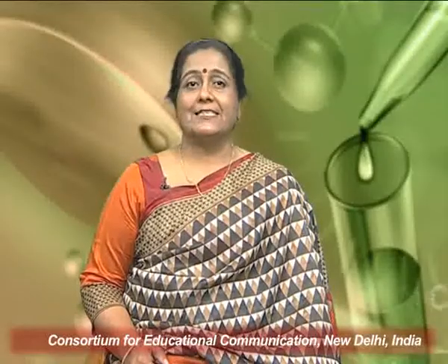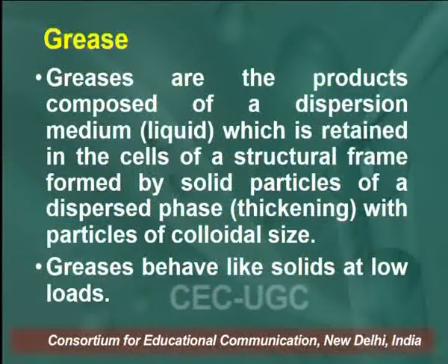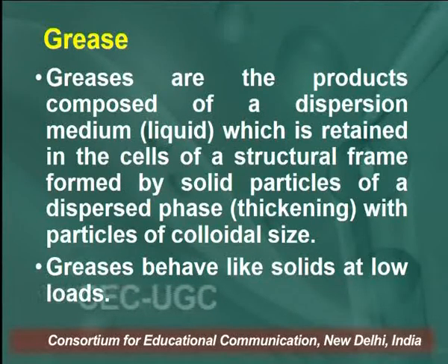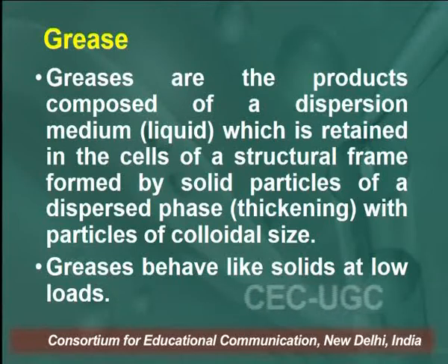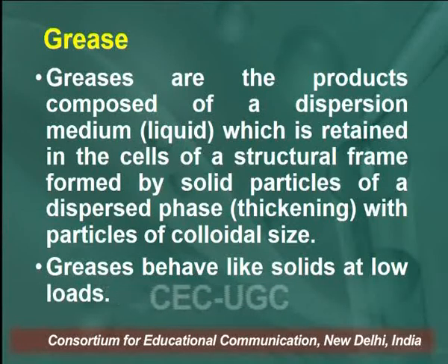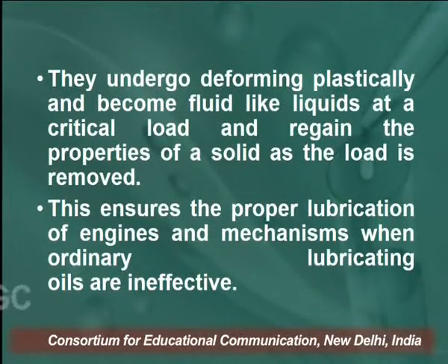Now let us discuss the greases in detail. Greases are the products composed of a dispersion medium, which is a liquid, which is retained in the cells of a structural frame formed by solid particles of a dispersed phase, also known as thickener, with particles of colloidal size. Greases behave like solids at low loads. They undergo deforming plastically and become fluid like liquids at a critical load and regain the properties of solid as the load is removed.